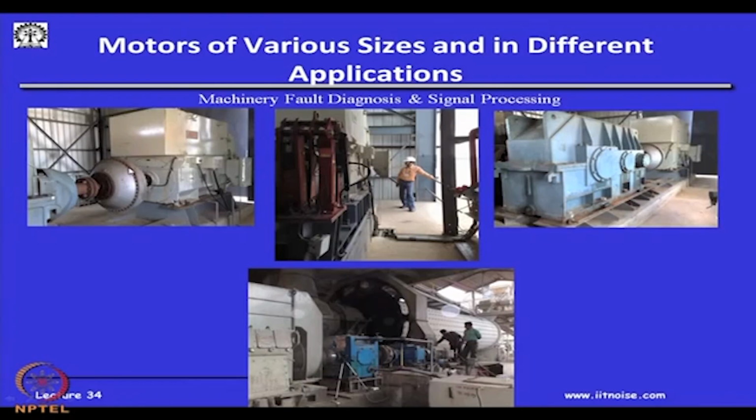In a gear coupling, as I was telling you earlier, the coupling allows for the thermal expansion, and if the motor is fixed and if the gear is fixed, there are bearings on which these rotors, because of thermal expansion, can slide. Otherwise, if they do not slide, if they are fixed, they are going to bend, and if they bend, again you know the same problem, the air gaps are going to change, then we will have pulsating forces. So, this is why in large machines we have gear coupling. Gear coupling, basically there are two gears, one over the other, and they will just slide, a little sliding is there. So, that takes care of the thermal expansion.